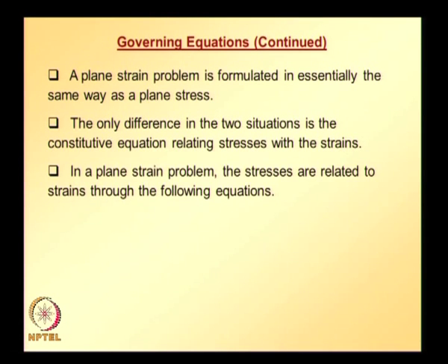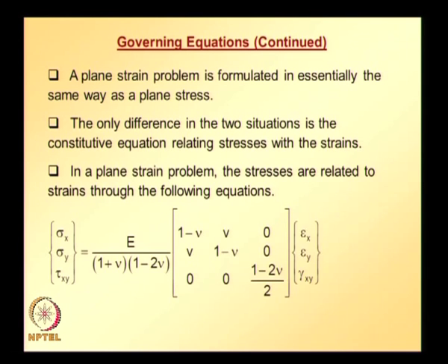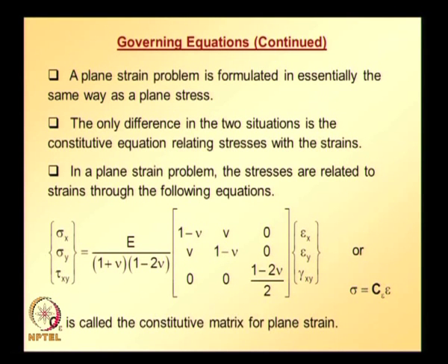In the plane strain problem, stresses are related to strains through the following equation. And this can be compactly written as sigma is equal to C subscript epsilon times epsilon, where C subscript epsilon is the constitutive matrix for the plane strain case.